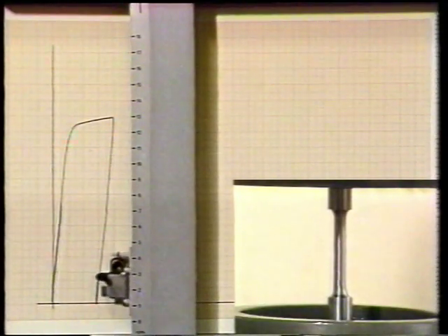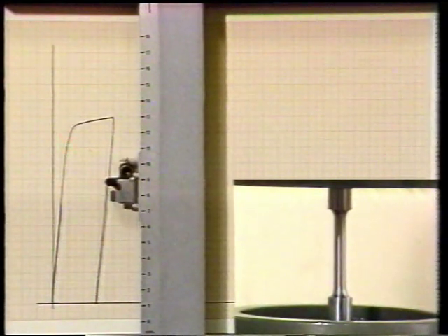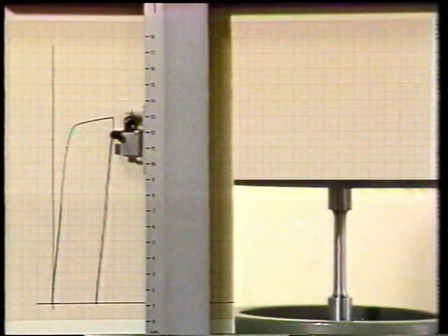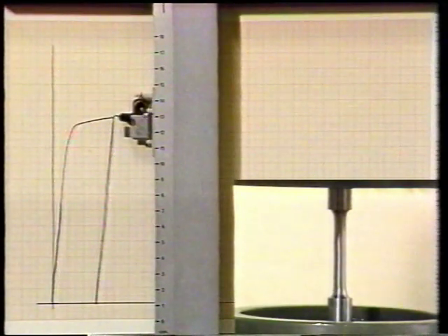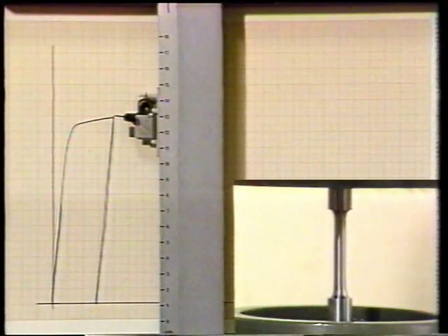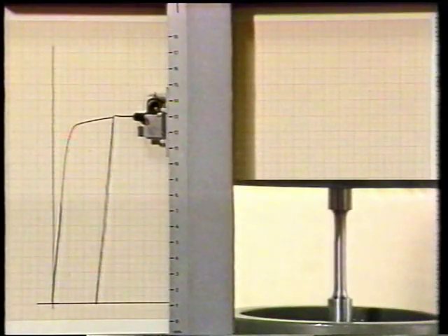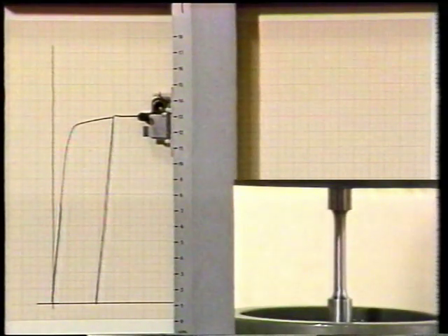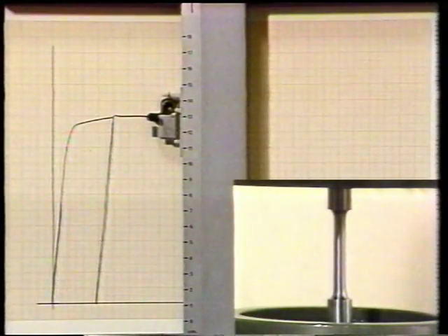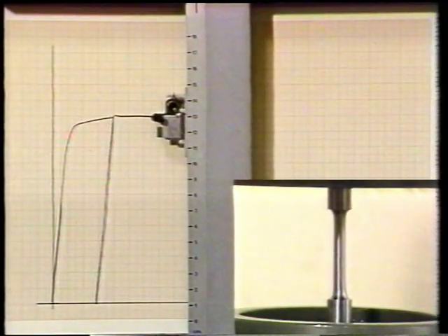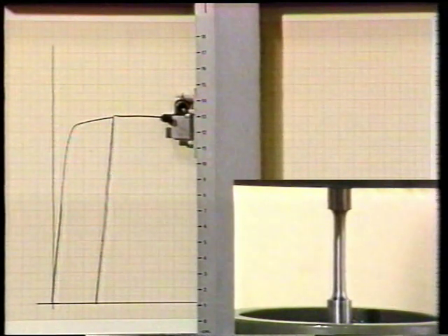Right, now when we reapply the load, the yield point is of course a little bit higher than it was originally because the metal has work hardened, and it will now pick up the original stress strain curve. The specimen is still deforming plastically. The rate of work hardening has reduced,